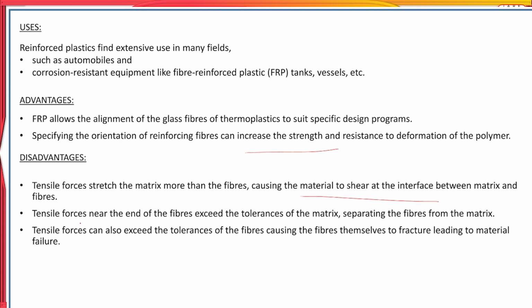Tensile forces near the end of the fibers exceed the tolerance of matrix, separating the fibers from the matrix. Tensile forces can also exceed the tolerance of the fibers, causing fibers themselves to fracture, leading to material failure.